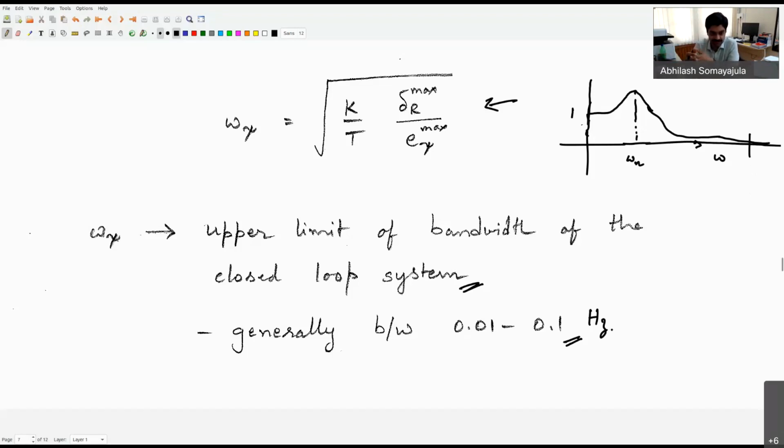In the high frequency regime, it acts like a filter, saying those frequencies will not be allowed to pass through. So bandwidth specifies the range of frequencies that the filter passes, the notional width of the channel through which input signals are transferred to the output of the system. All right, so that's what I mean by the bandwidth.